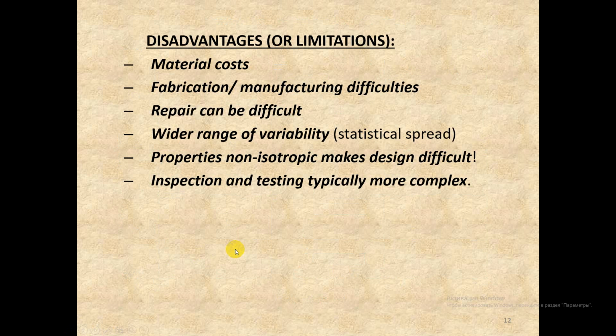And in addition to the high cost of the reinforcement elements themselves, there is the need for their protection from fire. The fact is that the glass transition temperature of epoxy glue is only 60 degrees Celsius, even in the case of the best epoxies.